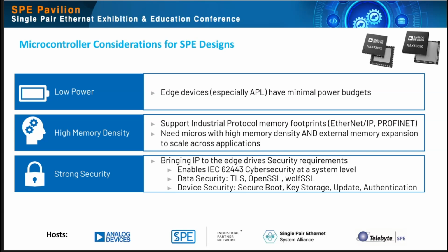And then additionally, a topic that we all love, the CRA topic, security. So you need to be thinking, are you compliant to the various regions of the world's cybersecurity standards that are rolling out? You can leverage tools like TLS and OpenSSL, as is shown here on the slide. But you also will need a high level of device security. So this includes secure key storage, update and authentication types of features. All things that you should be looking at, right? Long gone are the days where you can have a microcontroller with very little security.